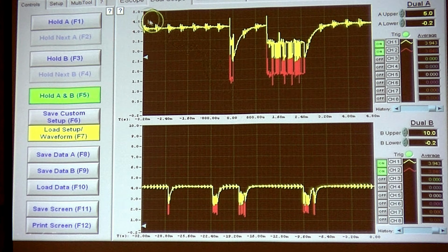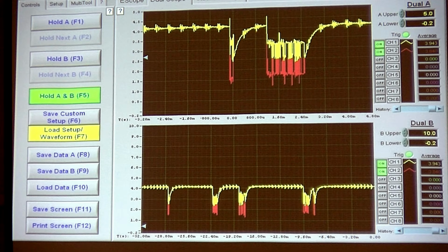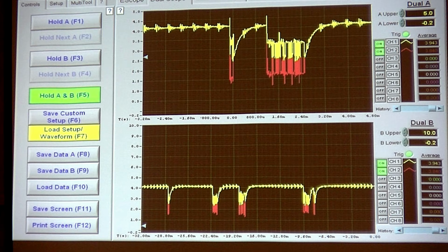If we look up here, we've got, what, 4 volts. What's that supposed to be at? 2.5, not 4. Somebody's pulling the bus high, and I'm not controlling it. As soon as we start to control it, that module can control it to what? 2.5. And when we let off, now it floats back up to where it's floating.